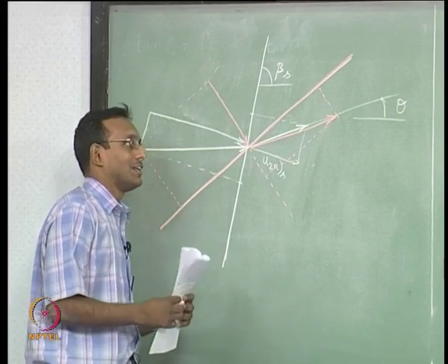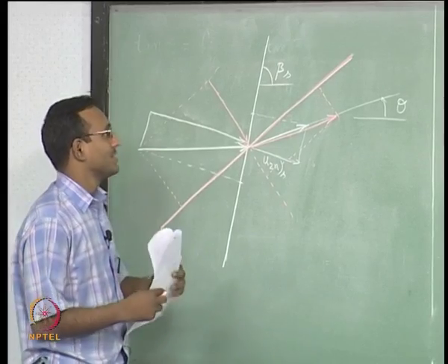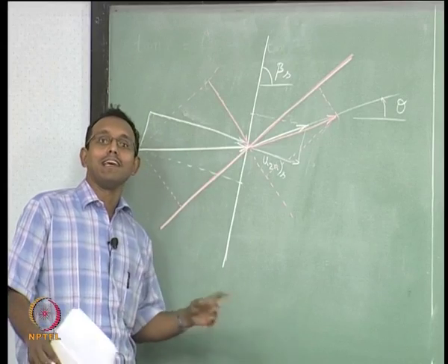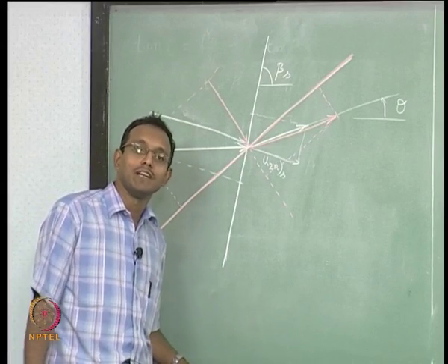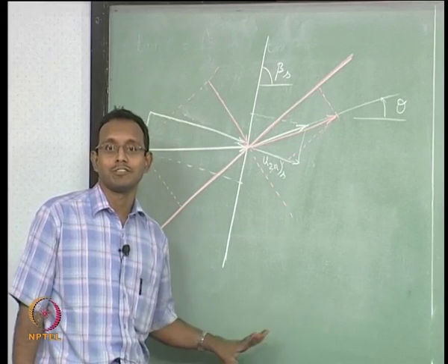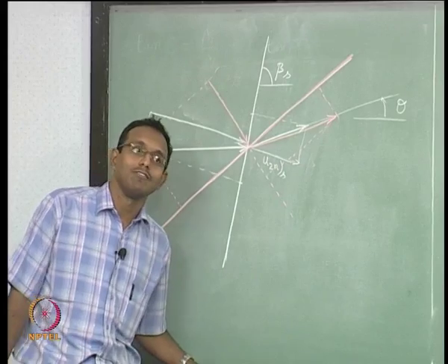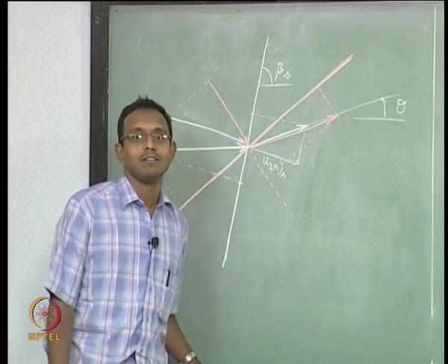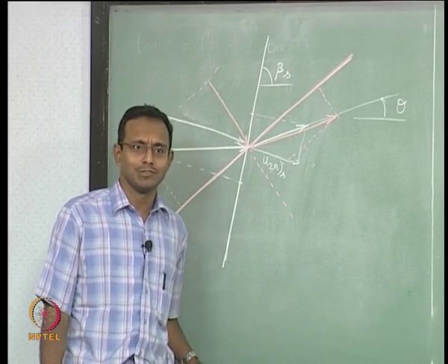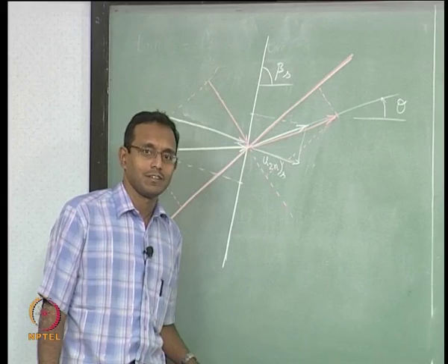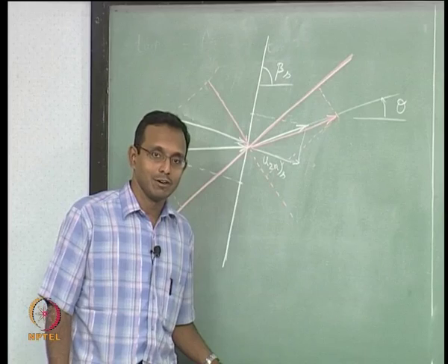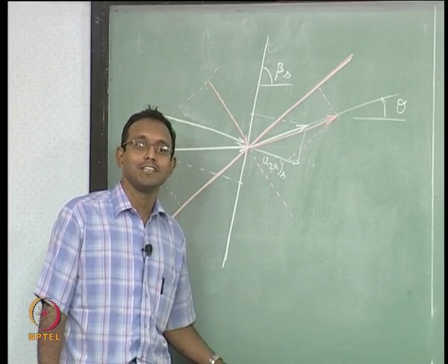Okay. Now, I will tell you one more thing. It so happens that we have two solutions, but in real life we see mostly only weak shocks. If I have a steady problem, I see only weak shocks. Till now, I have not seen a steady, stable, strong shock solution. And I have not seen anywhere in literature also stable, strong shock solution. That being said, that does not mean people have not observed strong shock solutions. They have observed it, but in unsteady problems.